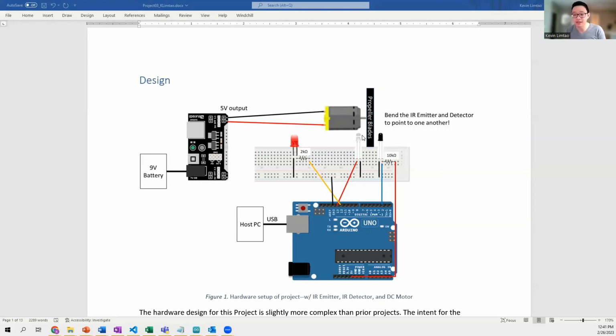It's just that because I wasn't getting enough light output from that LED to get to the sensitivity levels I needed, I opted to forego that series resistor. The photodiode circuit is very straightforward.